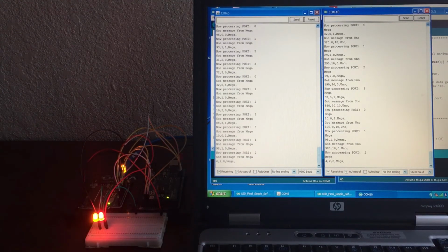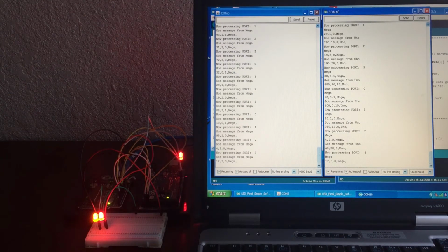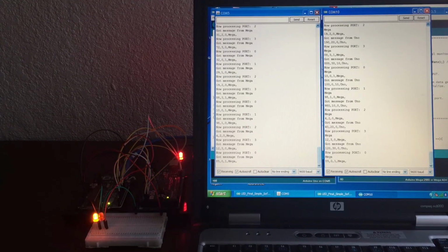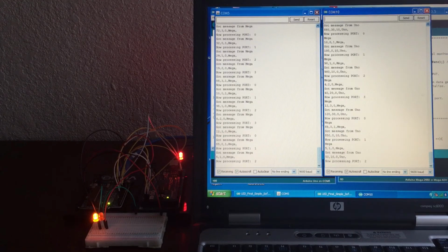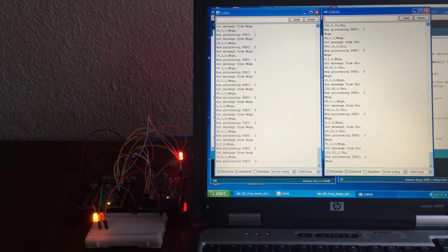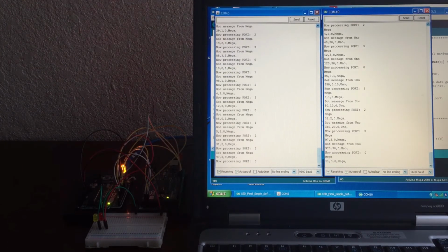But keep in mind that if you read 3 of the 7 characters in a string from the serial port, and then you do some stuff, if you read the serial string again, it'll be pointing at the 4th character. And that's why I clean out the serial port just prior to using it. It ensures a clean data line.